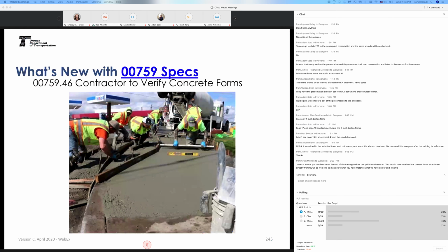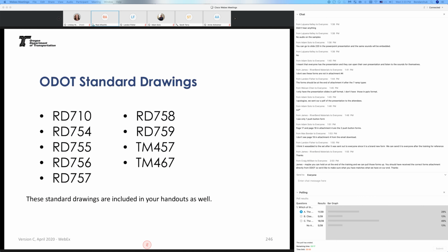Last here, typical of what we've been seeing, and we'll talk about that in the next section, the top 10 for failed ramps. Quite a bit of failure happens during the finishing, not during the form stage, not during what the contractor submits in the plan drawing. There's just minor inconsistency during the finish form. So contractors should be checking forms on wet concrete as they're moving, because that's a crucial and important part. So that takes care of this section.